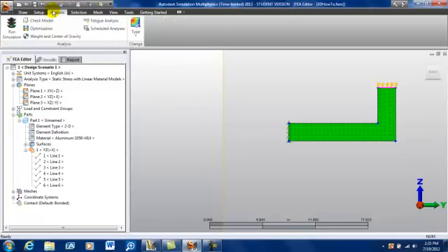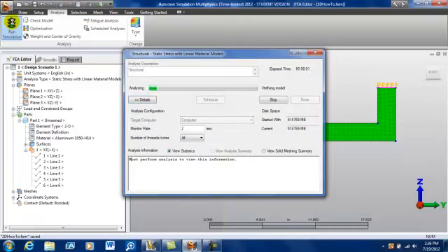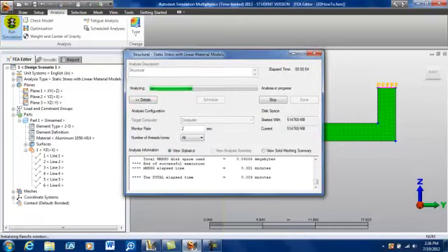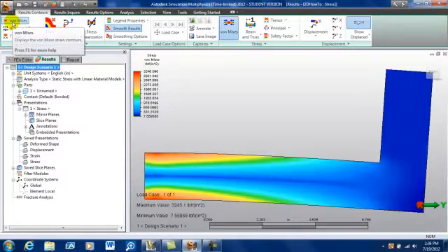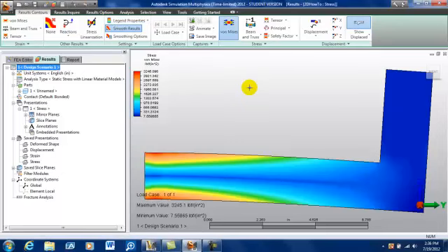So I'm going to click on Analysis and Run Simulation. And again, the purpose of this is just to show you quickly how to set up this type of problem. All right, we have results showing von Mises stress. It's occurring at a maximum right down here. The blue is very little stress at all.